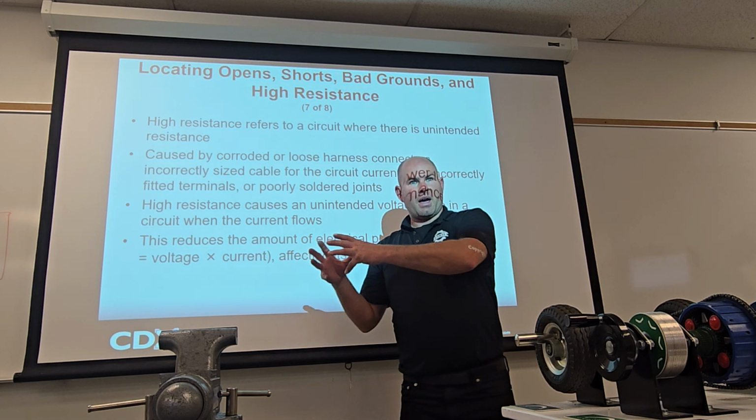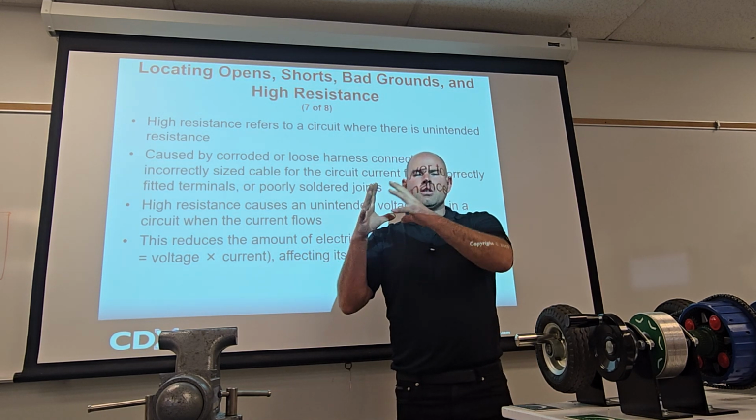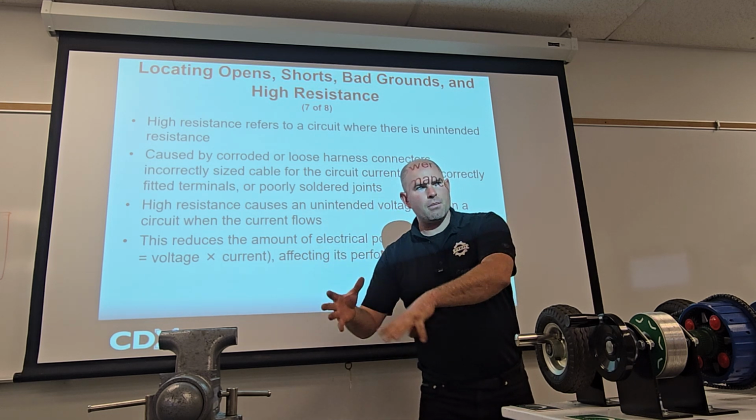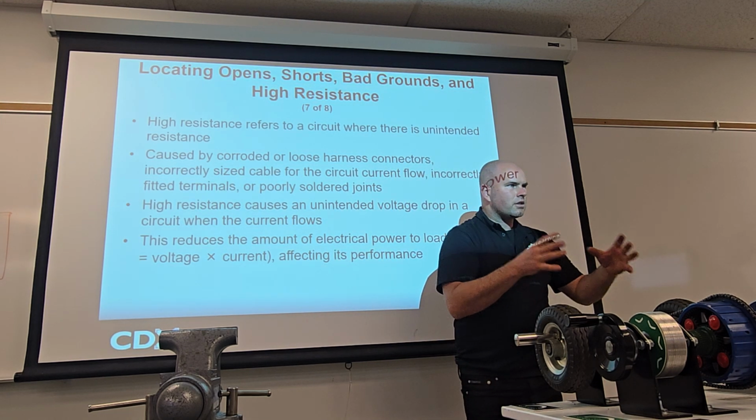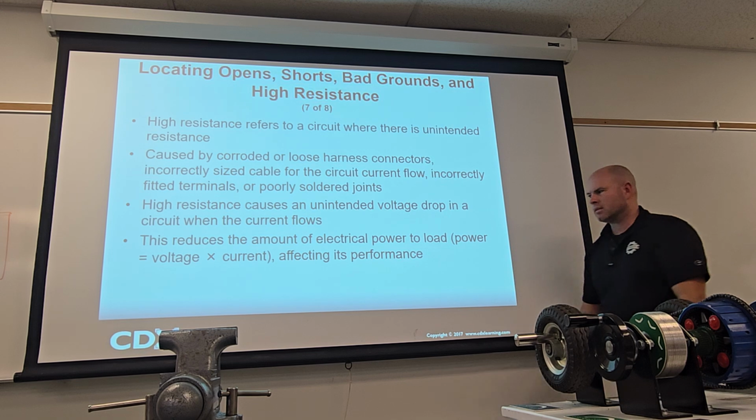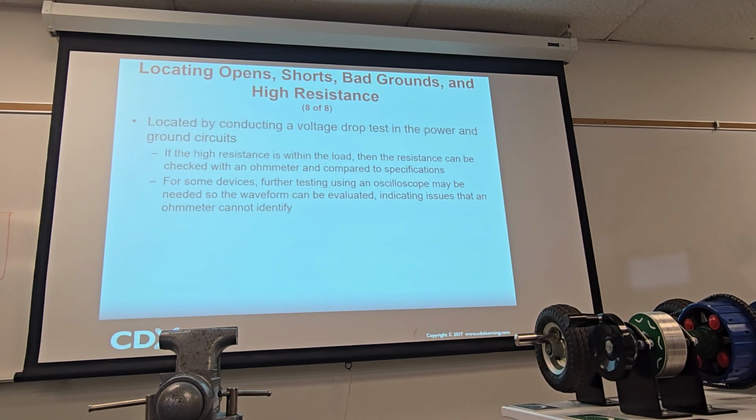That could be, yes, a dead battery. But that could also be unwanted resistance in your cable, in your solenoid, right? So we have to troubleshoot these things. Cool. Same with a dim bulb.